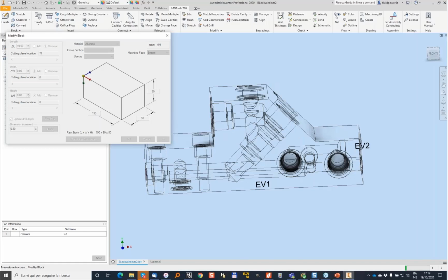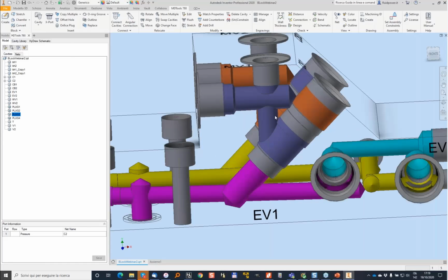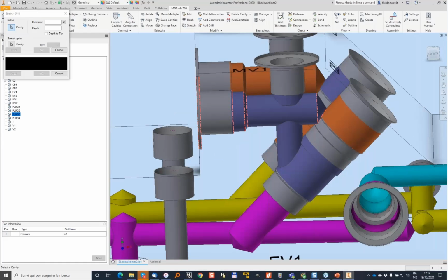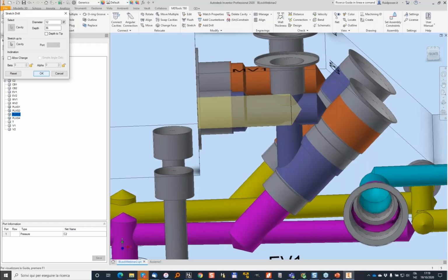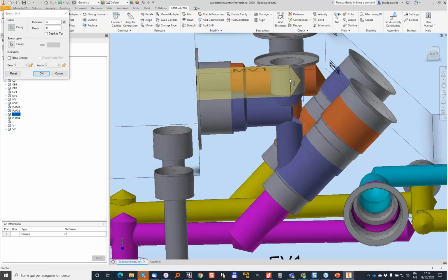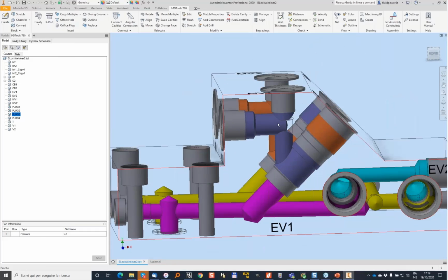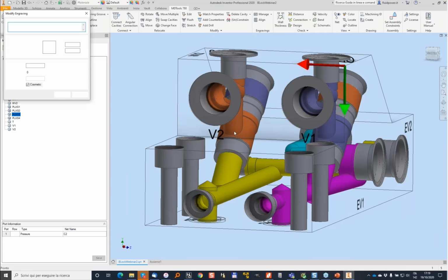When you do that, MDTools will shorten the block, but sometimes you will need to fix the drills in this case, because that's a limitation for non-rectangular blocks. In this case, these two drills are not lying on the external faces, so MDTools is not making them shorter. Let me move the engraving, and also this one, we move it up.